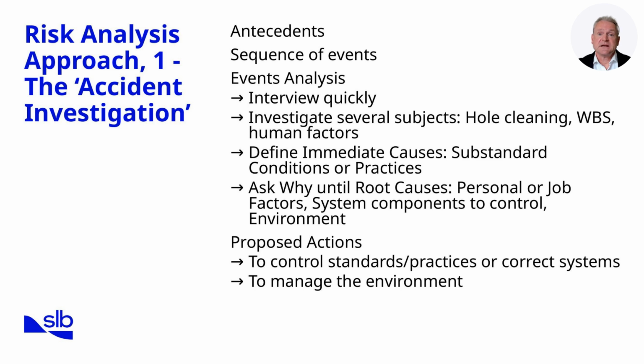The accident investigation approach to risk analysis works by deconstructing what has already gone wrong. It begins with identifying antecedents, the conditions leading up to the event, and then mapping the sequence of events. An events analysis is carried out through quick interviews and wide-ranging investigation across areas such as hole cleaning, well barrier systems, or human factors. The immediate causes are then defined, often traced to substandard conditions or unsafe practices. But to prevent recurrence, we go deeper by repeatedly asking why.